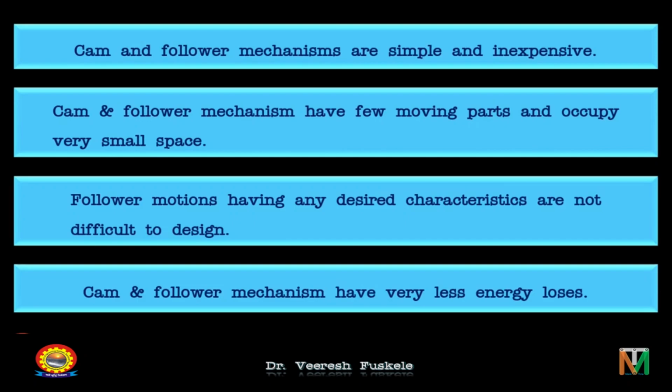It's this range of freedom in cam and follower design that gives engineers the ability to create unique mechanisms with only a simple rotational input. In any translation of motion, there is always some loss of energy. Cams will always have very minimum energy losses due to the fact that the interface between each part is such a small area, thus there is not a lot of friction. For these reasons, cam and follower mechanisms are used extensively in modern machinery.